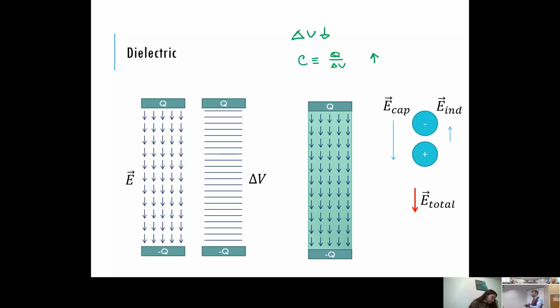Oh yeah, rooms with centrifuges are the same way. You guys deal with centrifuges, right? Usually you don't put a centrifuge into a really bulletproof room. What you do is when you put a centrifuge into a room, you make sure that one of the walls is weaker than the rest of them, so that if the centrifuge ever blows up, you know exactly which way the explosion's going.